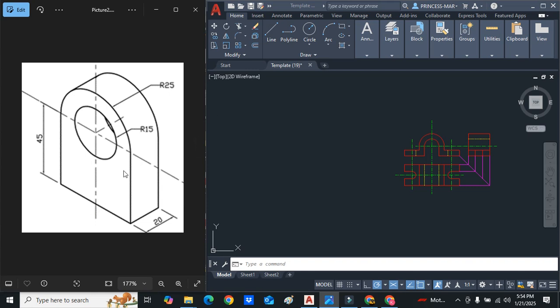So with orthographic views, you're drawing the front, the end, and the plan, which are the sides of the drawing. The front is usually the side that shows the most detail. In this drawing, the side that shows the most detail is this left side. So we have to look in the direction of that side to get our view. If we're looking in this direction, we're looking to the right, so this view is going to be placed to the right of the end view.